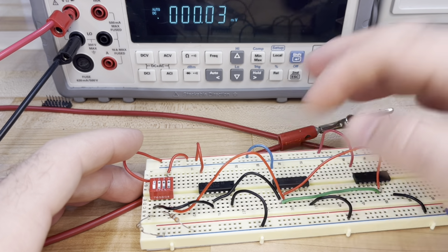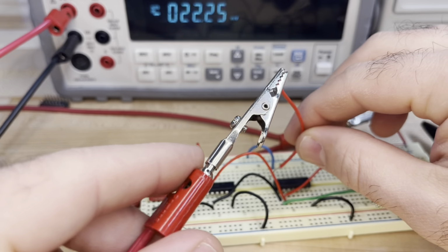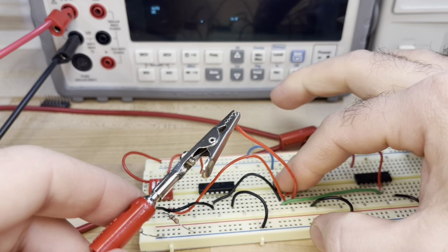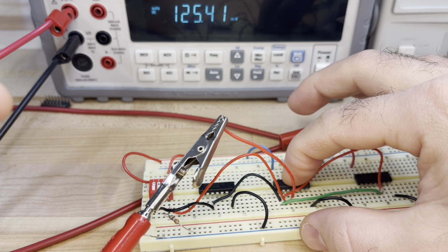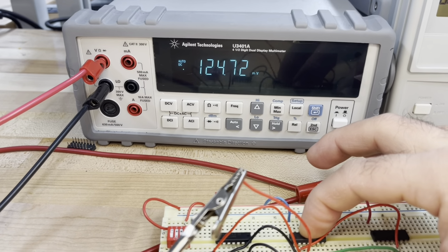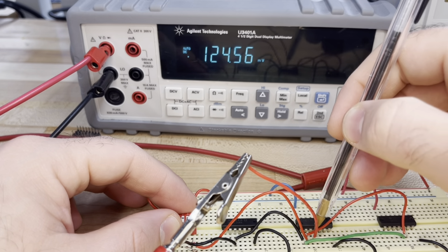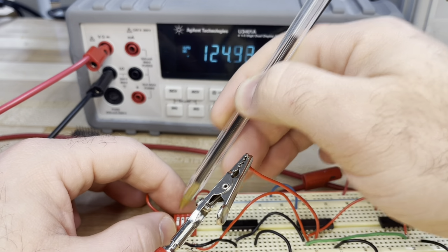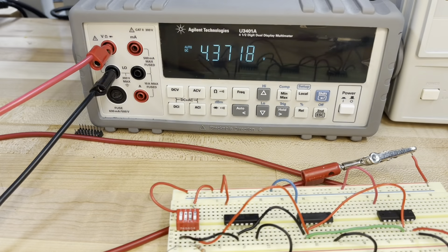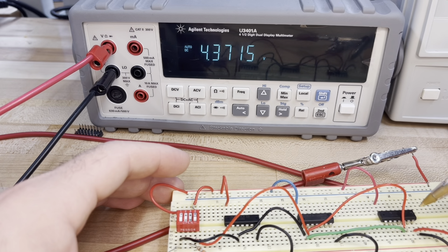Now we go to the AND gate. We see which pins we used, pin number 1 and 2. So the output goes to pin number 3. If you forgot, you just need to look to the inputs and then go to the data sheet, determine what is the output. Next, you go to the multimeter, change the switches to the proper positions. Remember 0 mean on, 1 mean off. Same thing for the OR gate. And in that way, you would be able to fill the table.